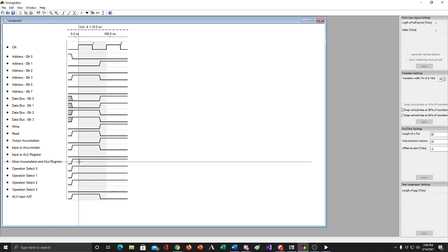We made sure not to wipe those registers with the clear line. And we just had to ensure that our pathing was accurate so that it was definitely sending the C value, the value in memory location 3, which we could see on the data bus here. So the C was being sent in the A direction here.